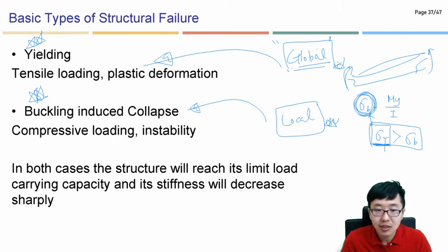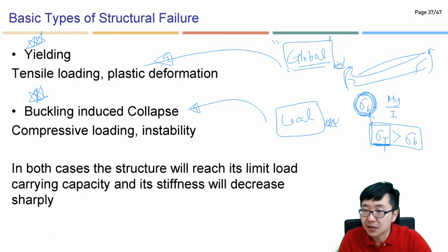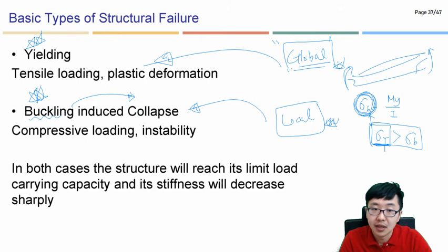But why do we need to consider buckling behavior? I have not explained buckling yet, but this is one of the reasons that we need to consider buckling. So we will bring these stresses obtained from the global structural analysis. But the other thing is here, buckling can cause the collapse, which means that the buckling stress can be much smaller, lesser than yield, but it can introduce the collapse.